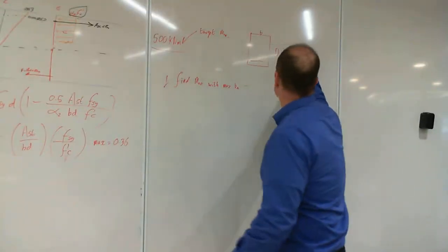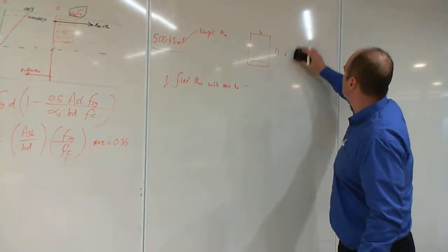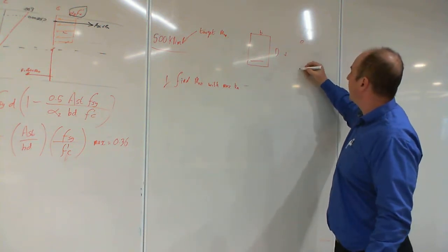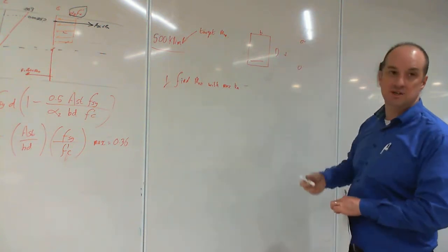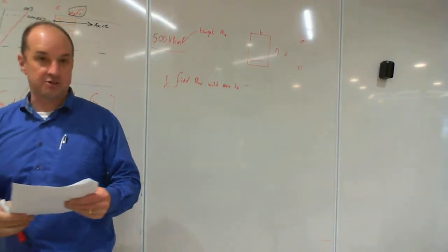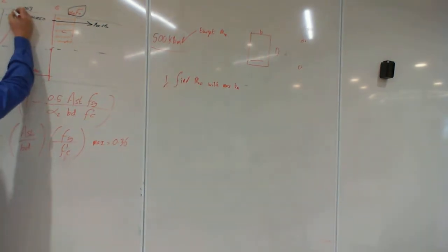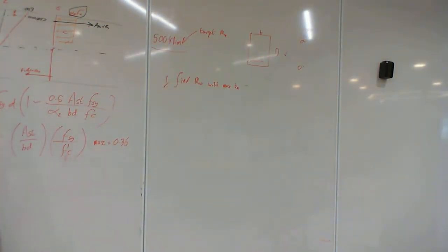Then we need to add some secondary steel. We need to add some compression and some tension steel. So the first thing is, let's see if that top steel yields. So you put it in a certain distance, there's the cover, centroid, do the triangles and find out if that strain is greater than or less than the 0.0025. So you see if the top steel yields.